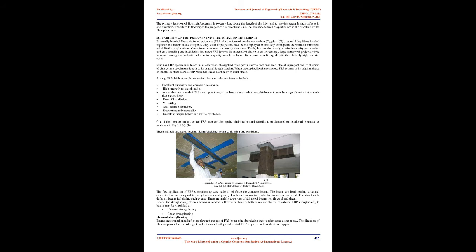Need of retrofitting in RC structures. The strengths of various types of concrete have increased from the low levels of 15 to 20 MPa to values in the range of 40 to 70 MPa. Such uses include increasing the load capacity of existing structures, such as existing parking garages, that were designed to tolerate far lower service loads. Other uses include seismic retrofitting, and repair of damaged concrete structures.